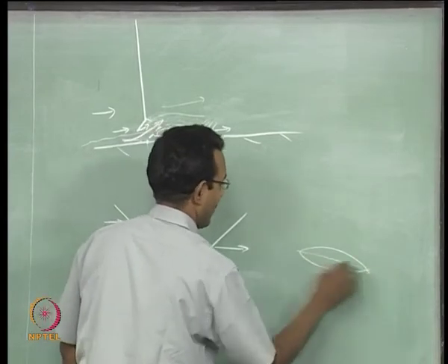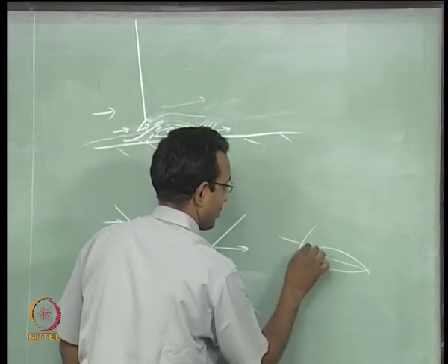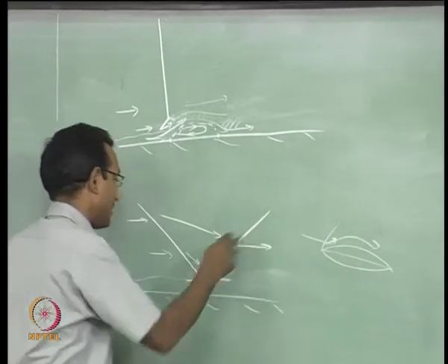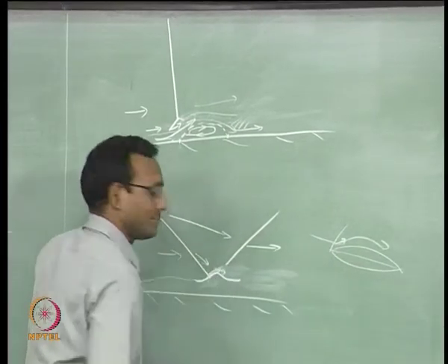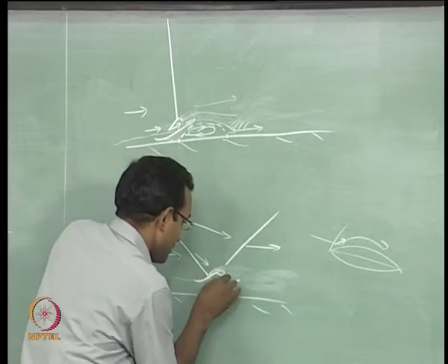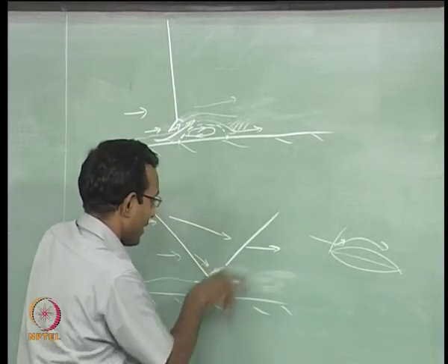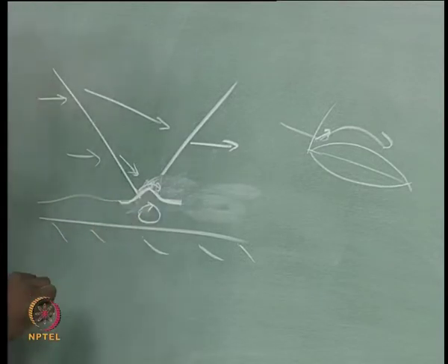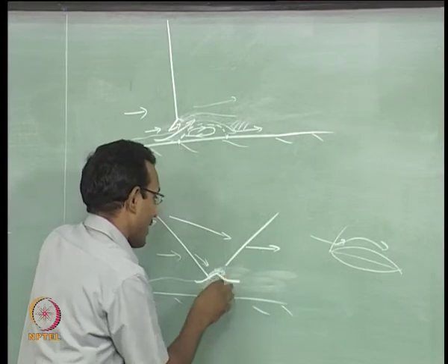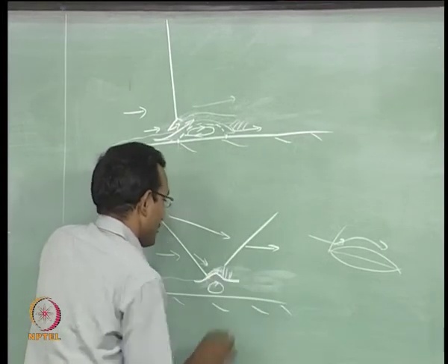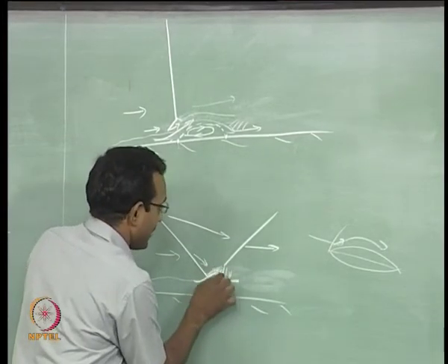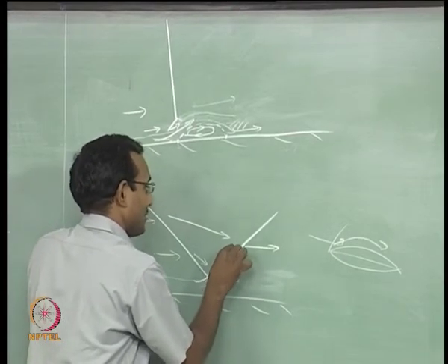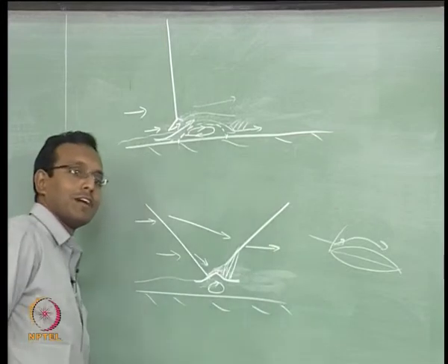This airfoil at an angle of attack, flow is going to come here, and then it is going to see all kinds of things after this, it is going to expand after that. Similar thing will start happening around this bubble, and at this bottom corner it is going to turn again. The flow field, because the recirculation bubble is like this, flow is going to turn back to straight, there will be compression waves here. All these waves interacting together will finally go and form that final shock which we have drawn already. It will finally form that wave.